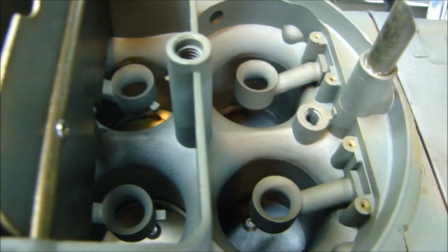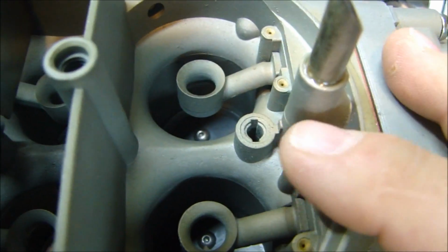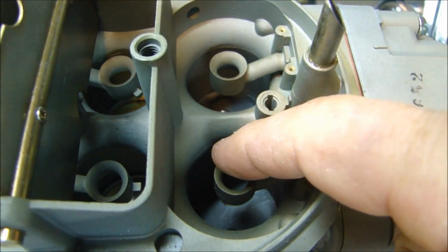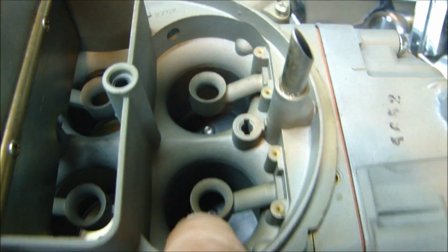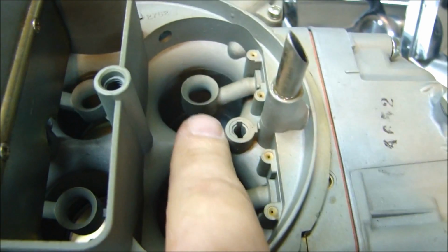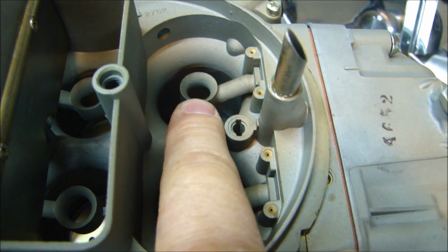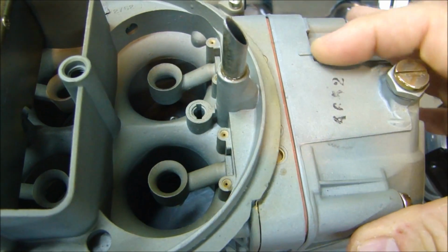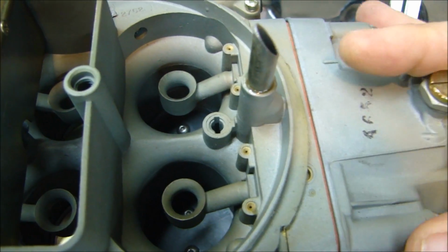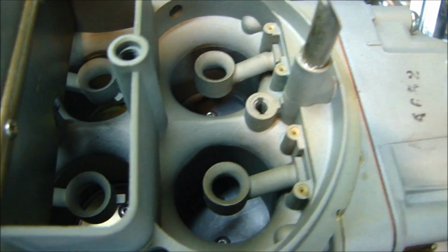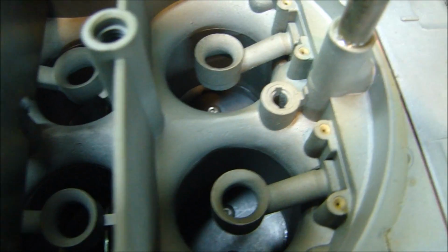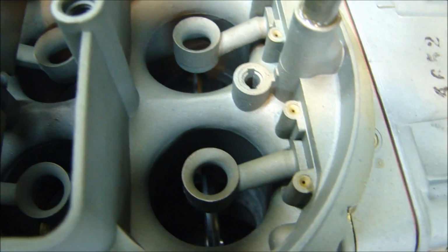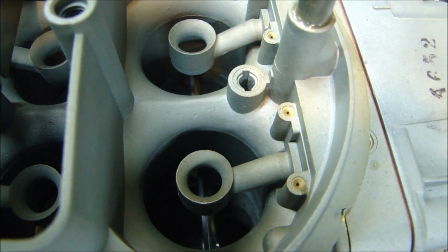So when you are at wide open throttle and you stomp on it, and when I talked about vacuum signal, you have air rushing into the carburetor. As the air rushes past the fuel metering ports right here, it draws a vacuum signal. The signal goes back into the float or the bowl of the carburetor, where the metering rods are, and meters the fuel as it comes out. Let me open this back up. Underneath the butterflies is where the atomized fuel enters the intake manifold.